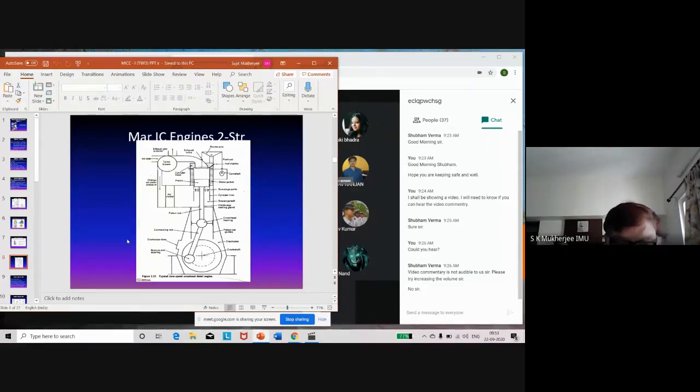So this viscosity is a parameter which is decided by the designer of the bearing or the machine, that this particular viscosity oil has to be used. And based on that, your choices for the lubrication is made. For a turbocharger, the lubricating oil for the bearings is different. For the governor, the lubricating oil is different.